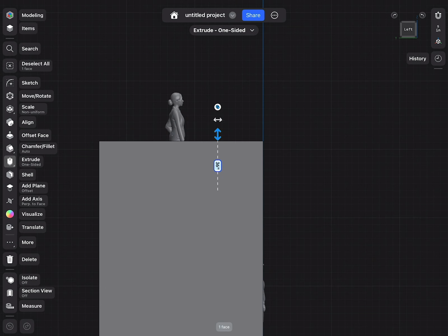And we didn't really talk much about construction codes and norms. So for example, we would need to Google how high is a handrail. So let me quickly Google this. Handrail height. So they say 34 to 38 inches.